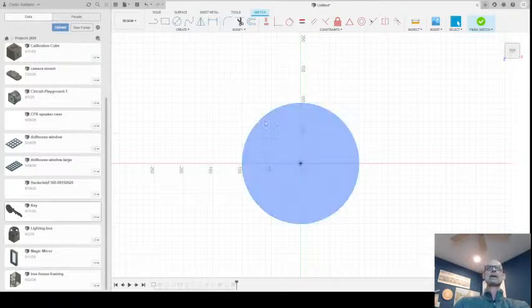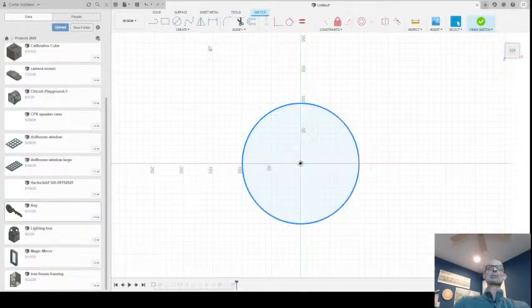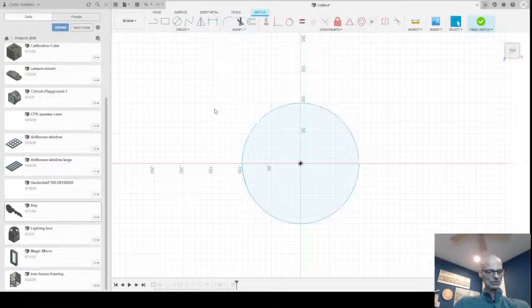And let's say I wanted more than just this circle. So we had the constraint earlier where I created a smaller circle and then I concentric constrained it to the circle outside of it. But we also have the ability to just create a new circle right off the bat. And for that, we can use the offset tool. It's over here under modify. It's also the O key, or if we were using our search, we can hit S and then start to type in off, and you'll see offset.